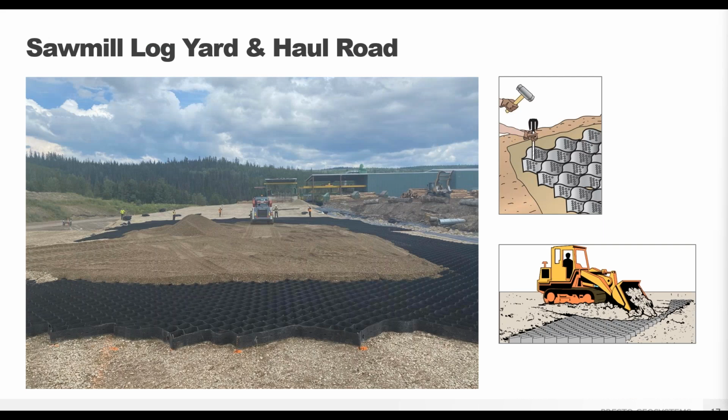This was a project for a sawmill in Canada. Spring snowmelt and fall rains cause flooding and soft, challenging ground conditions in the infeed area. And this photo is great to see how the GeoWeb was placed. Held open with stakes at the perimeter, and then the infill was spread.